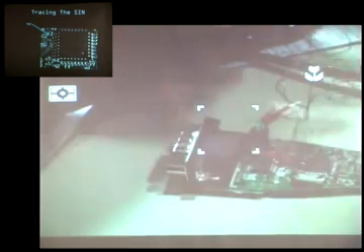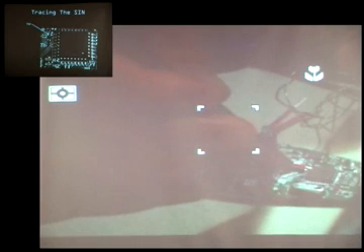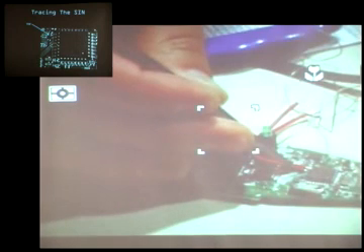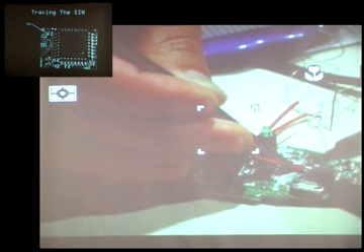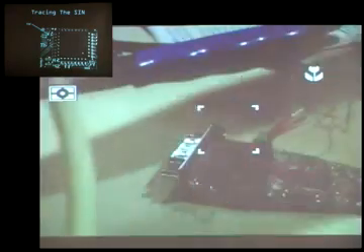And one thing I forgot to bring was my desoldering braid. So if I screw it up, well, I'm not going to screw it up. Alright, here we go. I'm very solidly locating the signal where it needs to be. I'm going to touch the wire first to melt the solder because I want to get that good melt pool going. And it's going to flow right up in the pin, wick right up. And there we go. That one is now attached to pin 17. Right there. So I've got that guy connected.